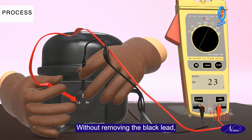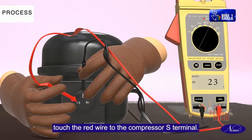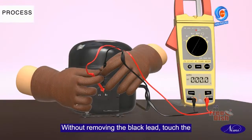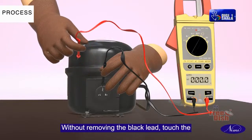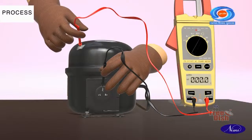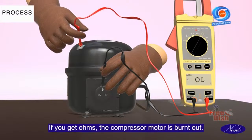Without removing the black lead, touch the red wire to the compressor S terminal. This will give the starting winding ohms. Without removing the black lead, touch the red wire to the compressor body. If you get ohms, the compressor motor is burnt out.